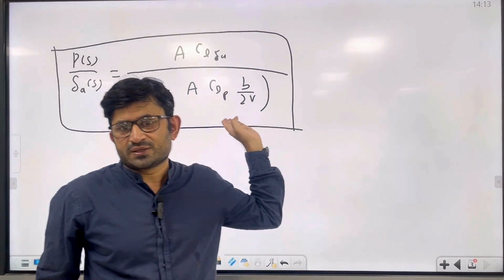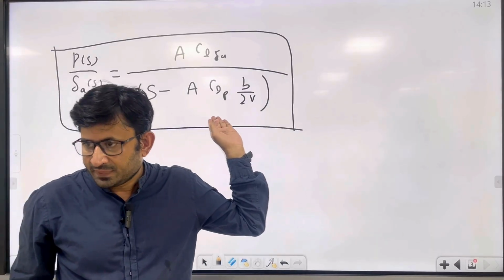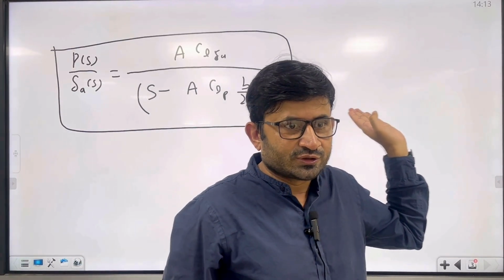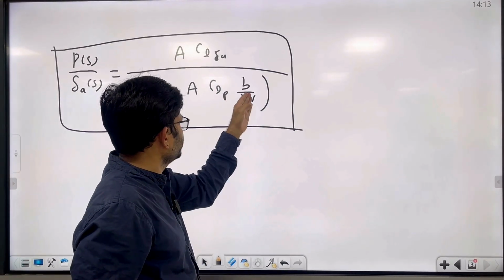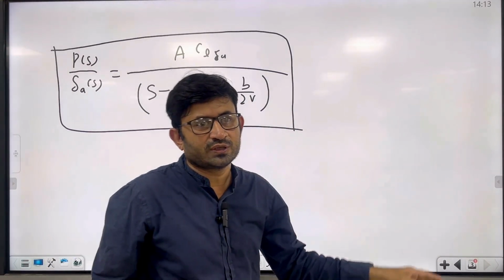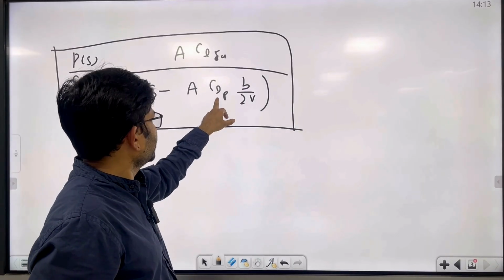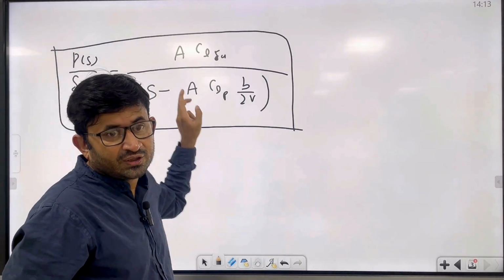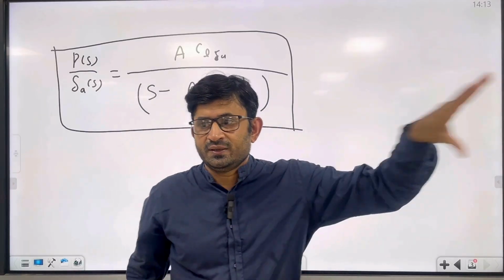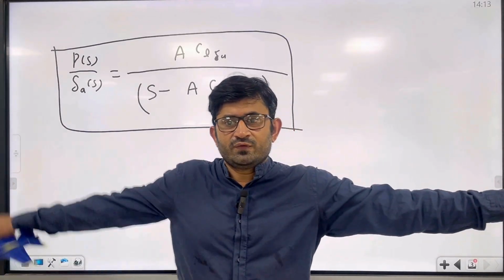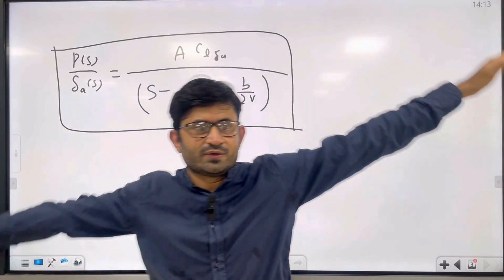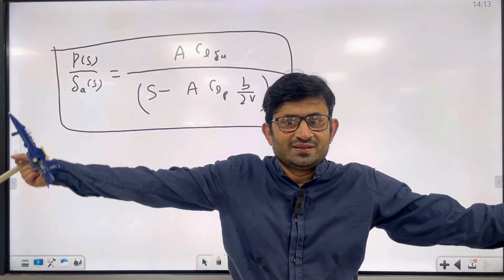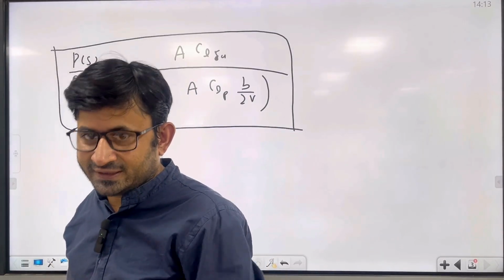Okay. A is positive, half rho V square S B divided by IXX, right? So that means A is positive, this is positive, B is positive, 2 positive, V positive. That means overall CLP is negative, so this sign becomes plus. So the pole will be negative. That is why when you take a roll, suddenly you bring back, right? The math is also telling the same.